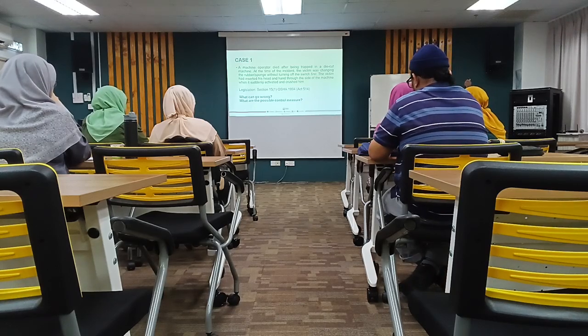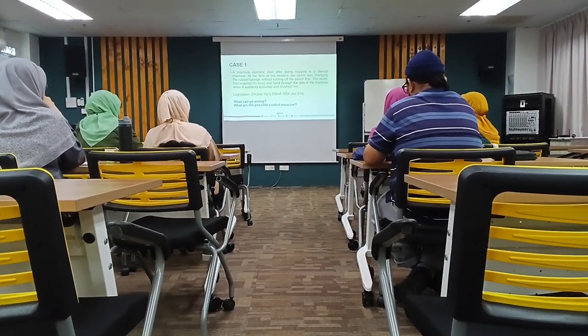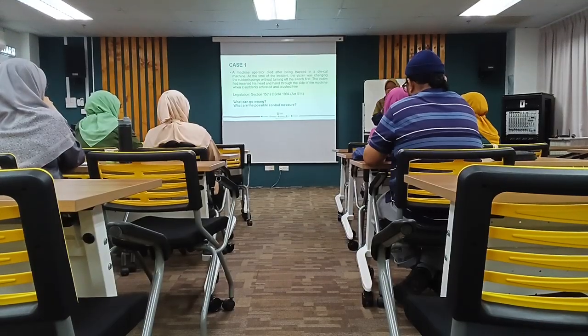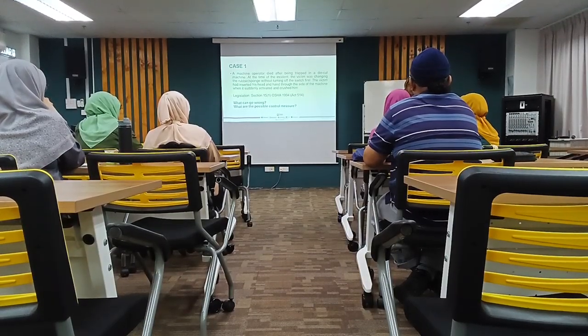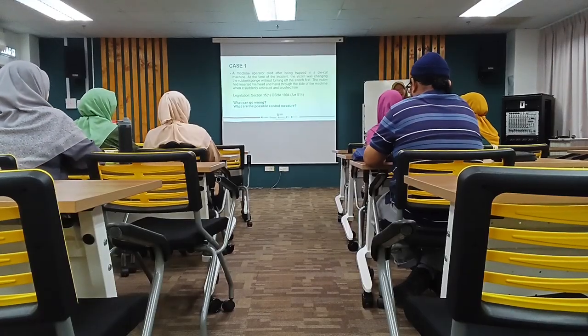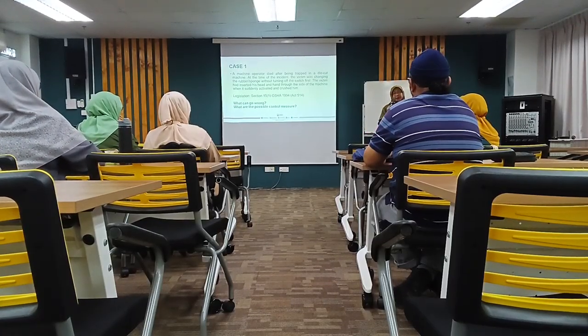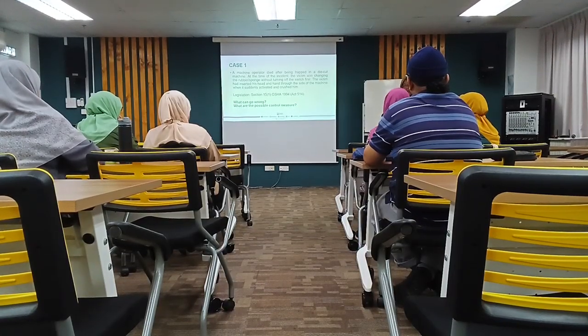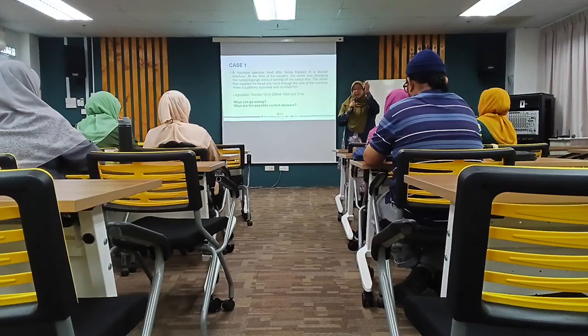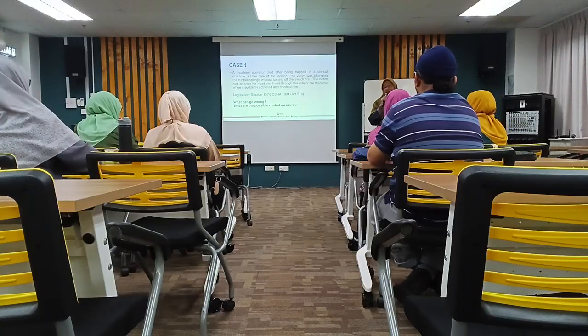First, there is no or lack of proper SOP where, when maintenance is done, the machine should be shut off. Are you familiar with LOTO? Not lotto, the 4 digit. It is lock out and tag out. That is very common in industry. It means that whenever maintenance is to be done, it has to be ensured that the unit is closed, locked from operation, and tagged. Tag means that it is under maintenance. That's what LOTO means: lock out and tag out.